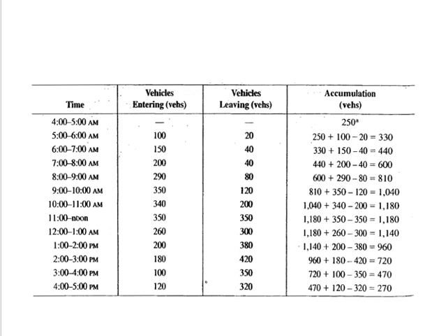What is your first count? Your first count is inside the area. So you take a count inside the area. How many vehicles are parked? How many vehicles are moving on the roads? Inside the area. You did not go to the boundary yet. This is your first count. So when you started your survey, now you know how many vehicles are in the area. This is your first value, the first value in the table.